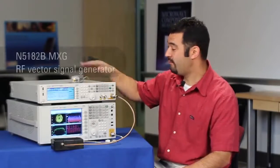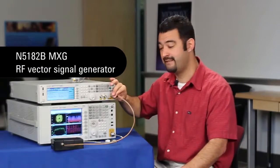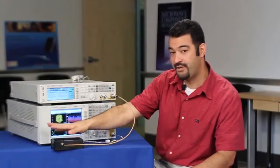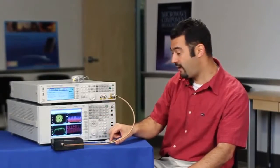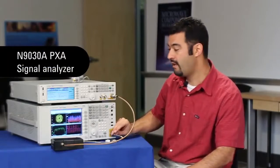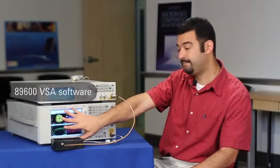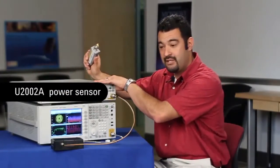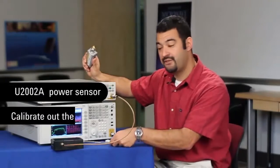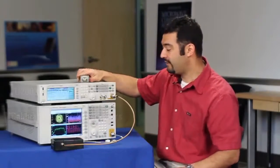In our setup today, we have the MXG vector signal generator generating a 100 megahertz wide QPSK signal. It's then being routed into our switch matrix, which has poor match, going into an external amplifier, and then into our PXA, where we're now analyzing it with our 89600 VSA software. We also have an external USB power sensor that's plugged into the back of the MXG. We're going to be using that to actually calibrate out the linear errors of our device. So let's go ahead and take a look at that.